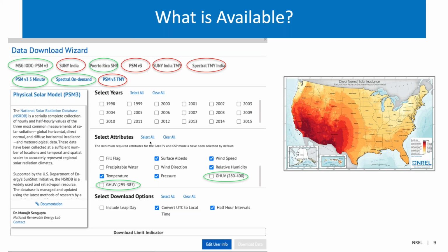So if you were to put your PV panel at a 30 degrees or latitude tilt, let's assume that, then what we would need to do is first convert our GHI to POA, and create the time series for all the years, and then build a TMY, use the same method, but create the TMY using that POA time series. So then you will get a more accurate representation of the TMY for that particular orientation.